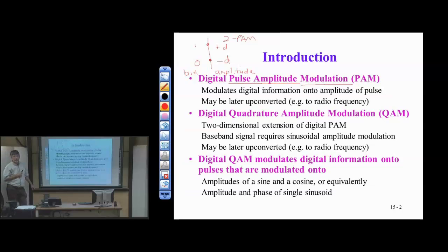So we've looked at baseband PAM, with no upconversion. We've looked at that in Lab 5 and in some of the homework problems. Not a problem, but one issue of using baseband PAM is that I need to have low frequencies available in my communication channel, and we don't always have that luxury. So in many cases, for RF communications, for example, I'd have to upconvert the PAM for transmission. Then I would multiply by a cosine to shift the center frequency from 0 to a new carrier frequency. So PAM may or may not be upconverted. Either way has an important role to play.